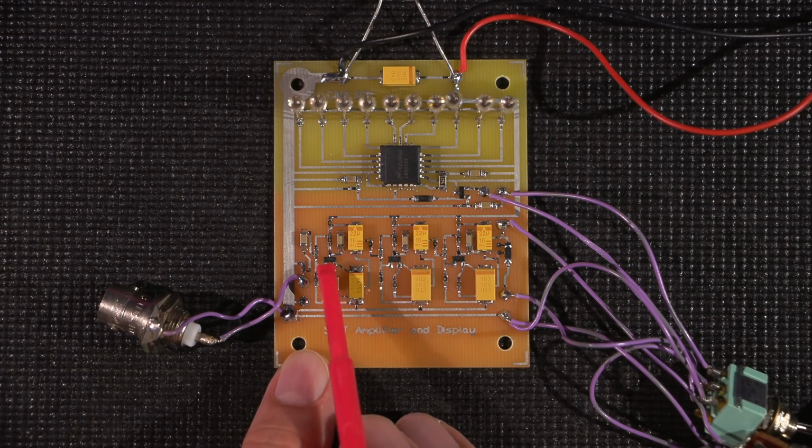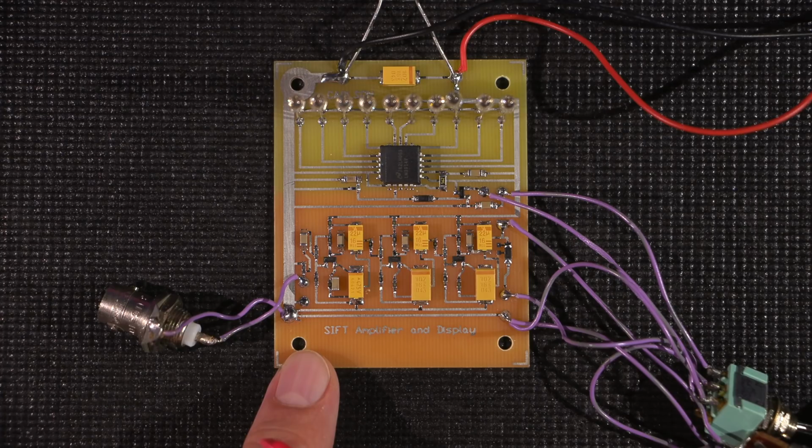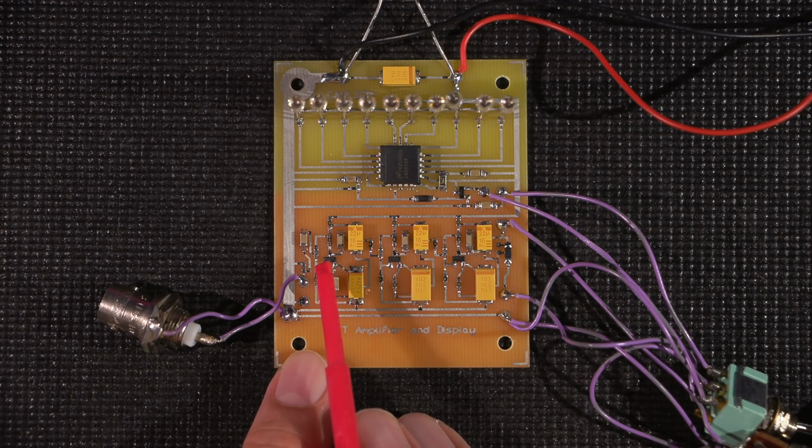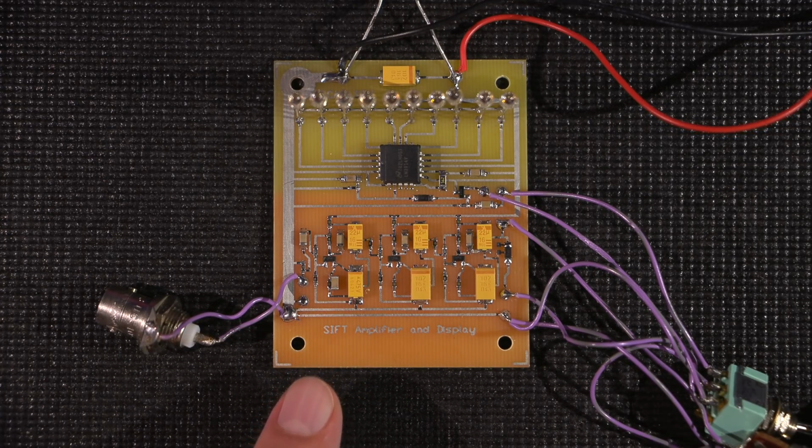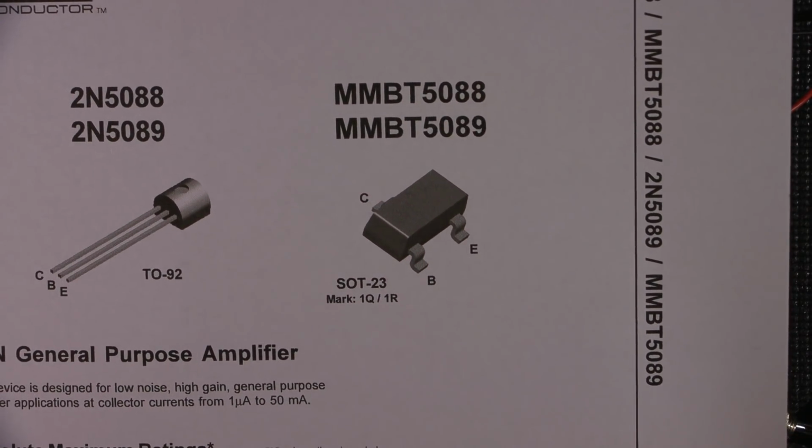So we know that the signal would be going through this capacitor and over to here. Now, if we didn't know what kind of a transistor this was, is it a FET? Is it a PNP transistor? Is it an NPN transistor? If we don't know what's going on here, we can very simply find out what this is, because the pinout for these transistors is very, very standard. So what we could do is just take a common data sheet. I have the data sheet for this particular transistor right here, and you can find these online, or if you want to save a piece of paper, you can just draw this down right now.